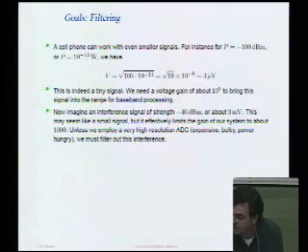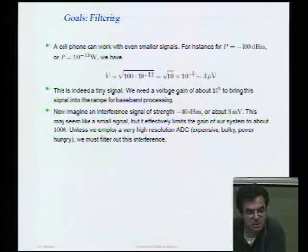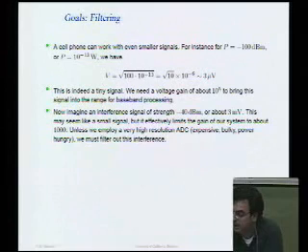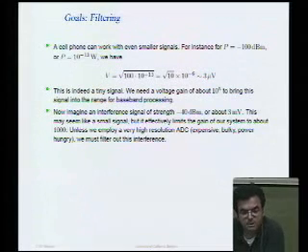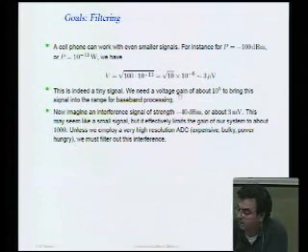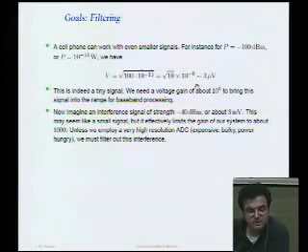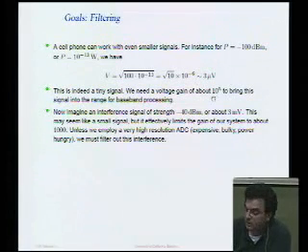But the problem is it's so much bigger, right? It's 60 dB bigger than the signal that we're trying to observe. And that means that if we just simply were to apply gain to our system, that interferer would actually limit the gain of the system to about 1,000. In order to take 3 microvolts, let's say up to 300 millivolts, in order to, let's say, digitize it, we need a gain of 10 to the 5. So if we can't get rid of this interference somehow, we can only have a gain of 1,000,